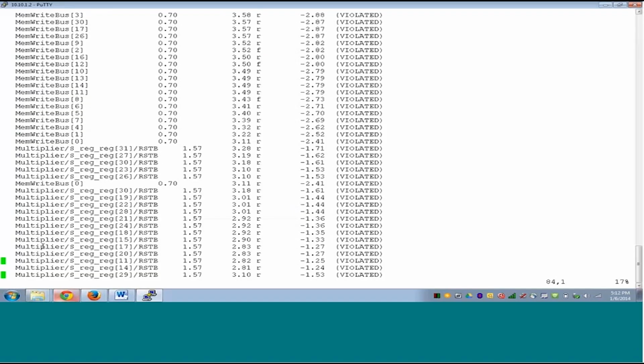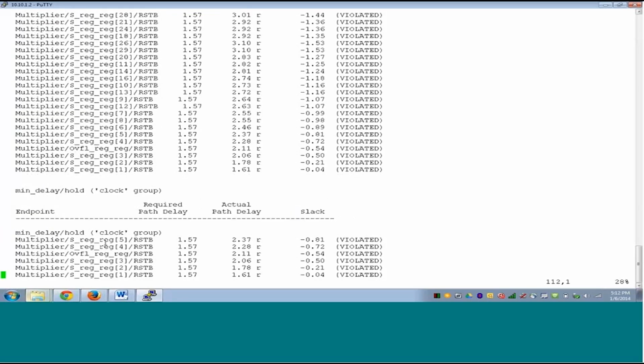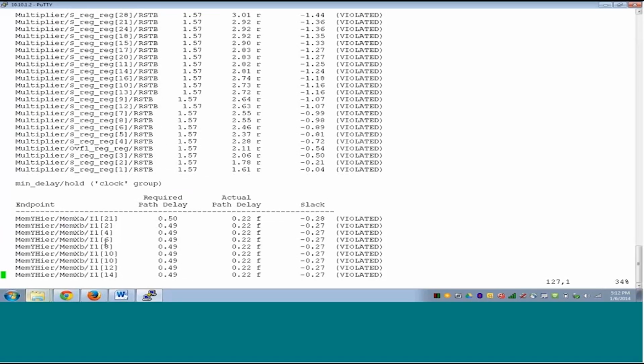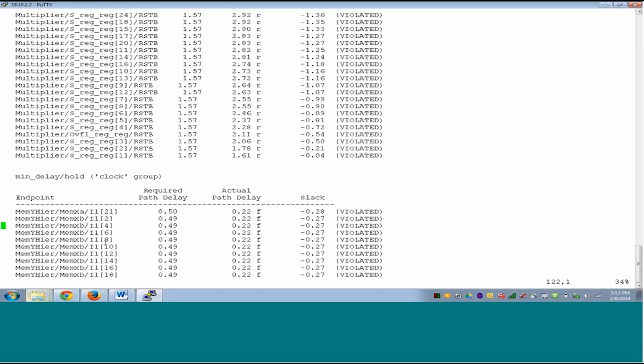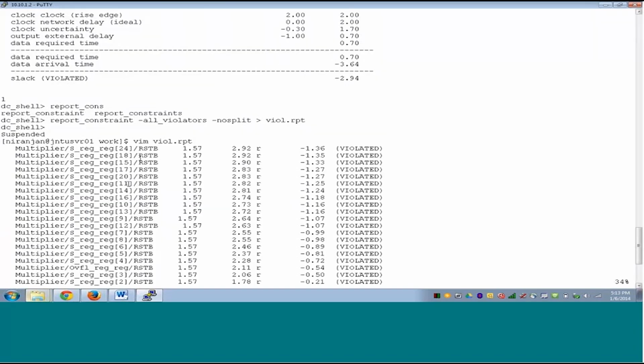Here we see that there is some pin that violates, and it's not a port. However, it might have a violation starting from an input port. This is just the endpoint. The leftmost column is the endpoint. Don't worry about the whole violation for now. Let me see if all these pins are reset pins, so they must be similar kind of paths. Let's see what this violation is.